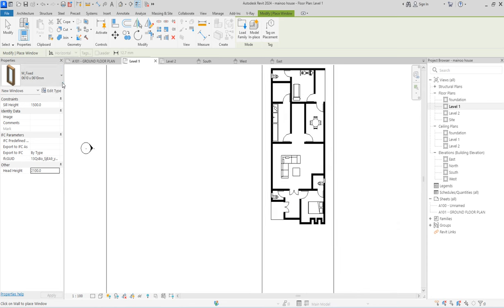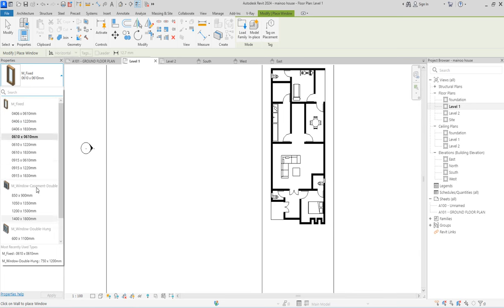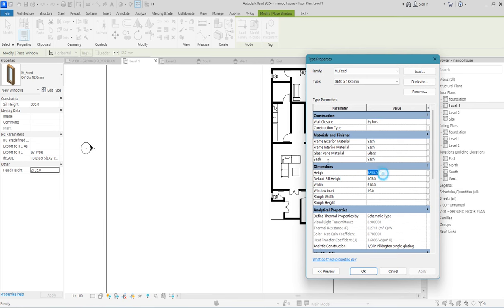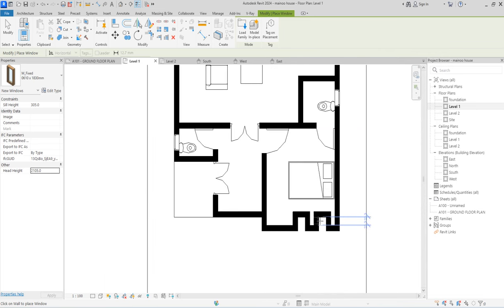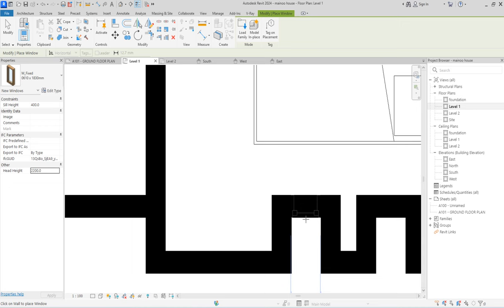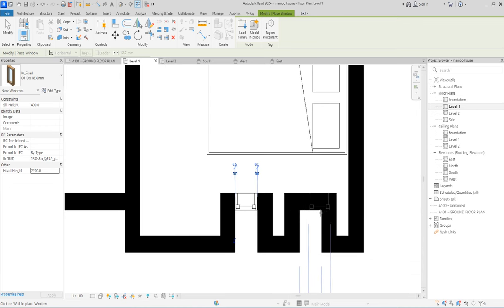Now let me work on the elevation, door of elevation. So I'm using this one, edit it. 1800 by 300 first. So I want to use that on this point. So what I need to do is to change the height to 2200. So that gives me what I need. So here as I stamp it here, stamp this one here as well.